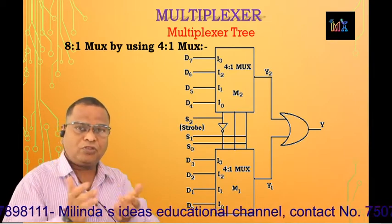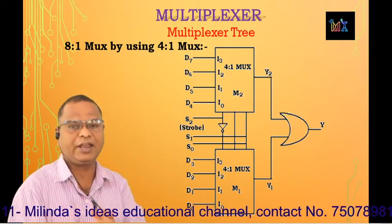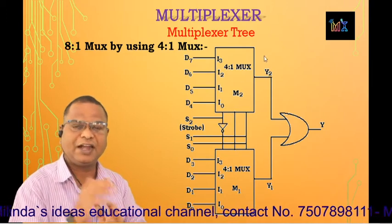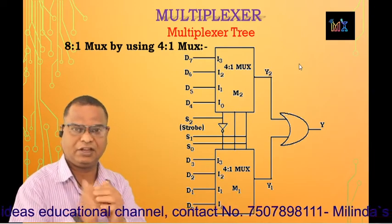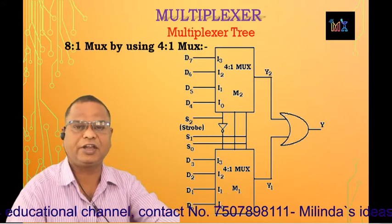The outputs of these muxes, that is Y1 and Y2, are connected to an OR gate, which gives a single output, because the output of an OR gate is the addition of its inputs. So the output of this circuit is Y1 plus Y2. When one of the inputs, Y1 or Y2, is high, the output of this gate becomes high because it is an OR gate.